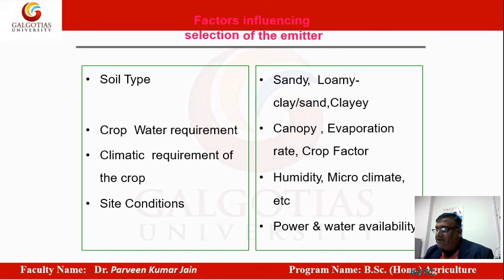And there is a dripper which has the capacity to release maybe 8 lph, or say 8 liters per hour. So you know that you have to keep that dripper open for 2 hours, and after 2 hours you will have reached around 16 liters, and then you could close down the system, as you have quantified the water which has been added to the soil.